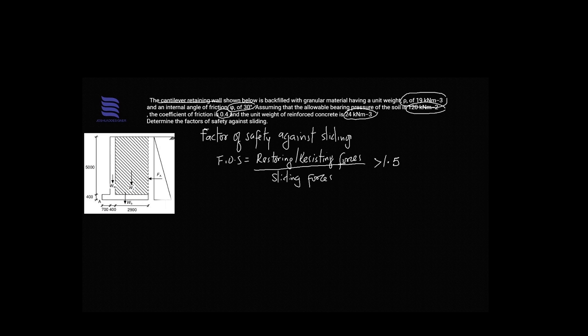Right, so the first thing we want to do is to check or to confirm our lateral earth pressure coefficient, which is called Ka. That's the lateral earth pressure coefficient, and this is for the active state. We have coefficients for passive states also, that's Kp, and we have Ko, right? So this is Ka, which we want to use for the active state. So that's the active pressure now.